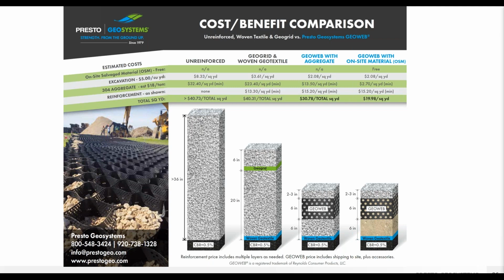Here we have just a really basic comparison for the GeoWeb system for load support applications. The comparison is going to be for the difference for both price and cross-section depth for an aggregate only, a GeoGrid and GeoTextile reinforced section, and then two different GeoWeb reinforced sections.